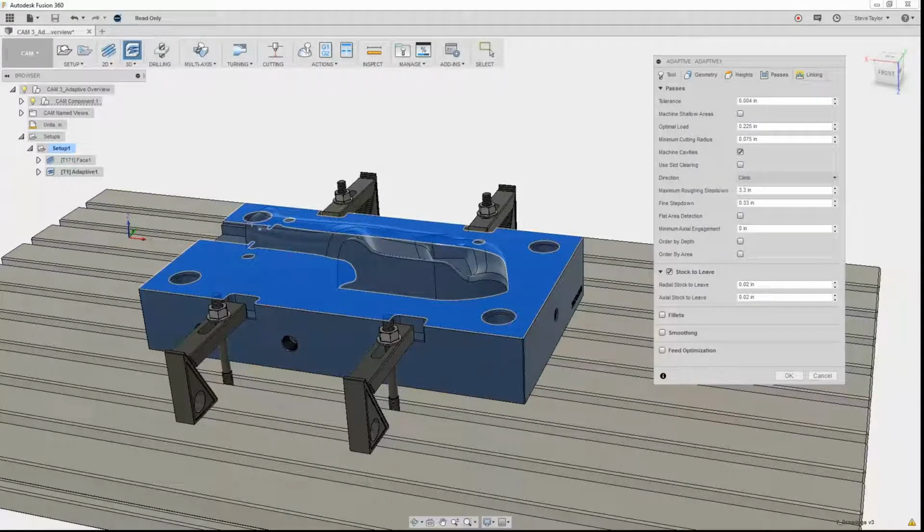Plus, by using the parametrics, it also means if we change the tool to a different length, it will automatically update to 80% of the new length for the maximum step down for that particular tool. So by not putting in the value there, but using the parametrics to calculate the value, if you change the tooling, it will automatically update.